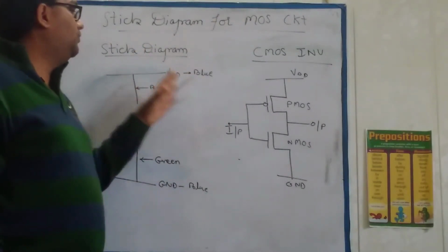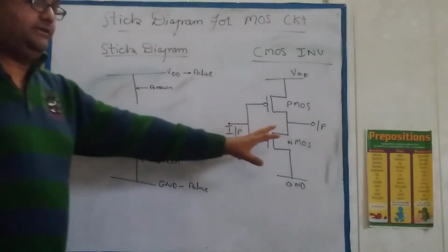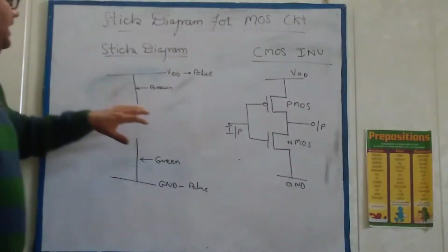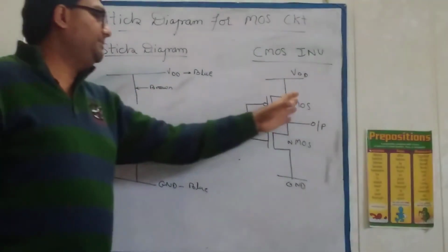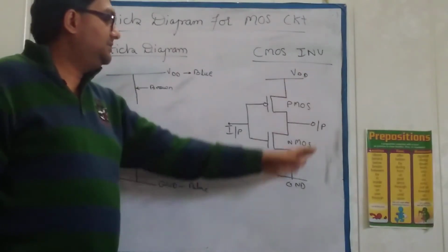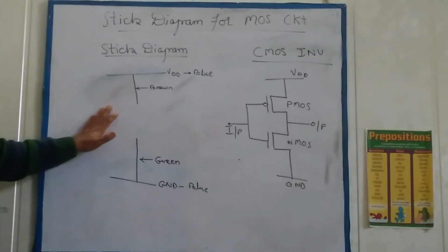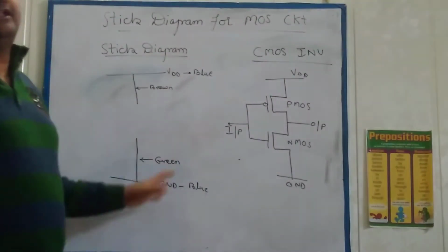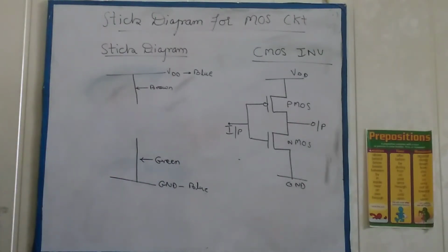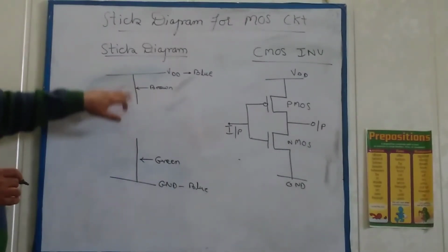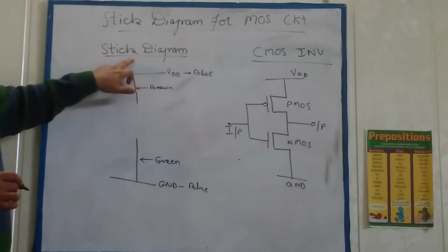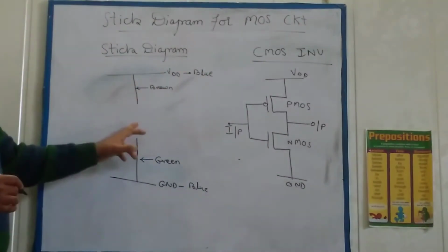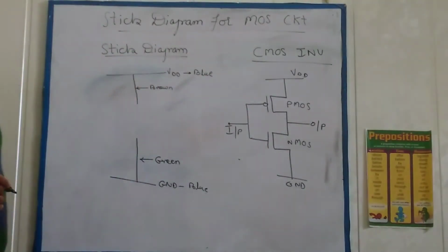Mainly we have to show the pattern of the circuit, right? So a circuit diagram is drawn with symbolic representation, and the pattern, or simply the layout, of this circuitry is shown by the stick diagram, right? We will not take any symbolic representation in the stick diagram, only the color combination, the fingers and the lines. Due to these lines, the name given is a stick diagram, right? So all the circuit is represented by the lines, that's why it is called a stick diagram.